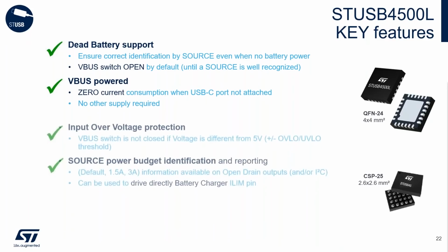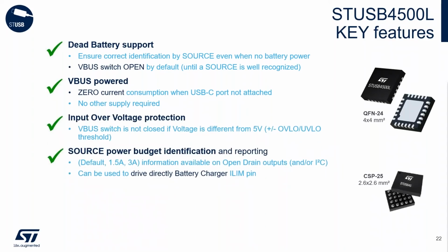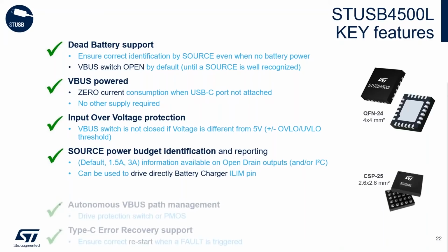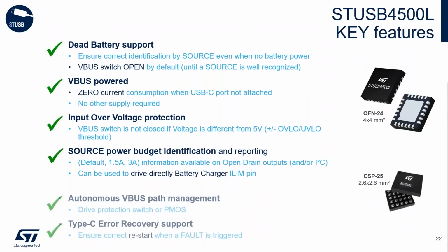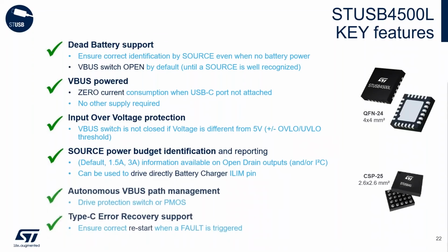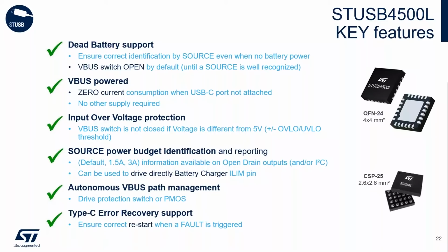It performs under and over voltage protection, of course, and it implements automatic power budget reporting, which is the duty of the sink, in order to set the maximum charging current and prevent from collapsing the source. And it implements especially an error recovery mechanism in order to restart from a false condition.